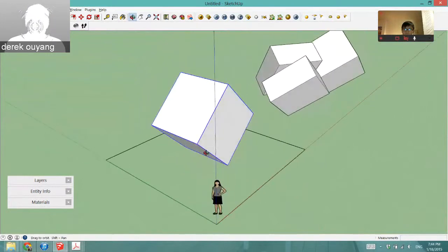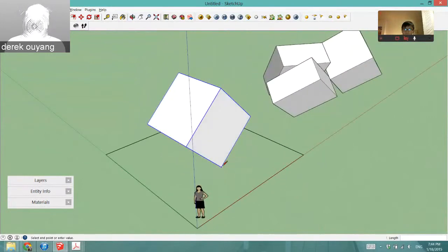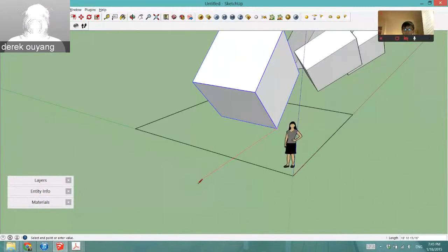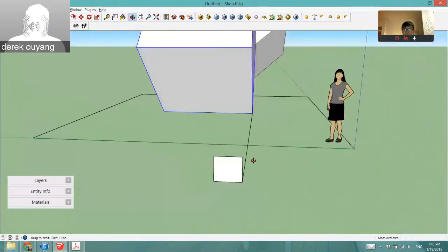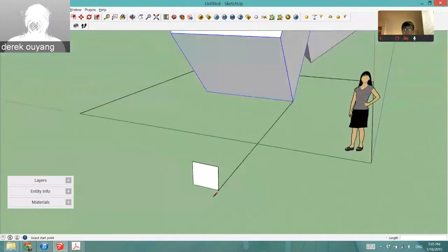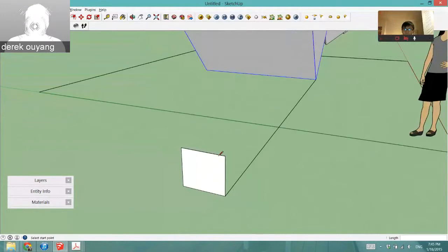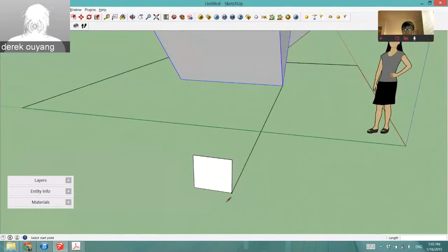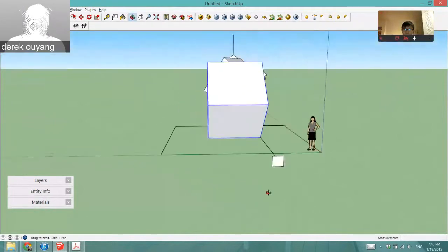So what you're going to do is simply draw a line out from the point in which you want to rotate and just project it far out, somewhere easily accessible, where then you can create a small little shape of any type that will be exactly the plane of rotation you want. Just imagine once you use the rotate tool, you're going to do it on this plane right here, and it'll be lined up to the axis you want to rotate in. So that's almost all we need.